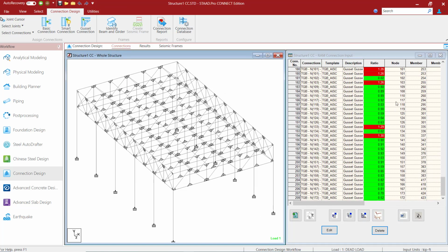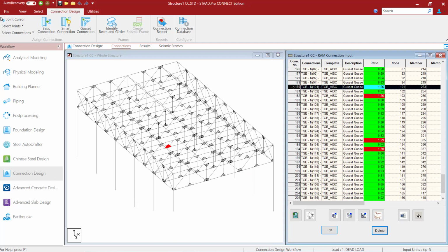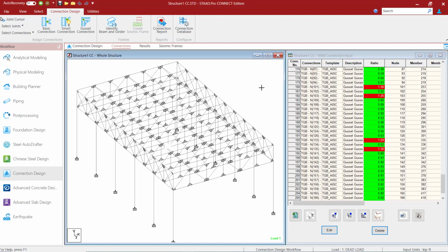All new connections have been added here, and exactly what I just mentioned earlier, we have several truss style connections that yielded an interaction ratio greater than 1.0, which means they're currently failing. I should definitely take a second look at this, maybe adjust the welding, maybe adjust the bolting, maybe I need to adjust the model itself. So that is what I'm going to want to do. And just like in the previous exercise, if I have connections that are geometrically identical, I can edit them together.